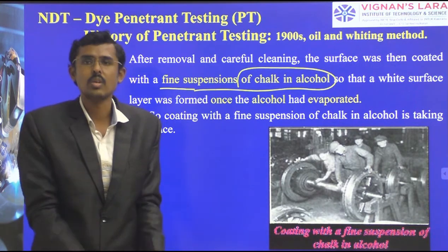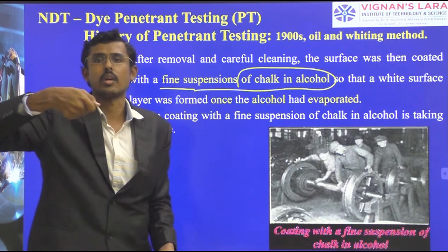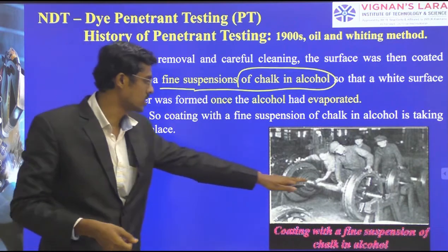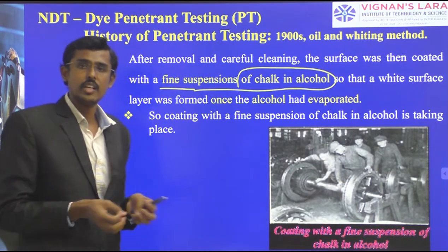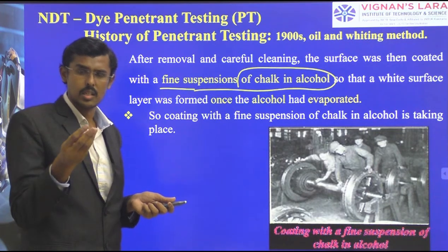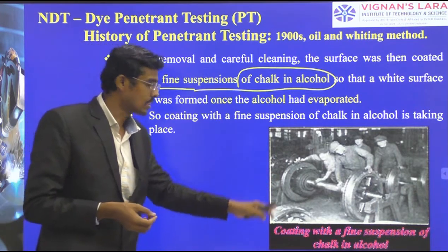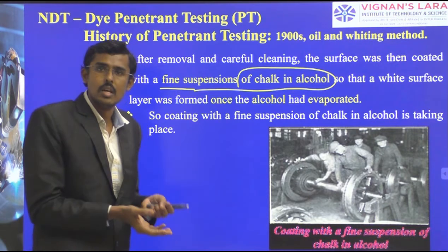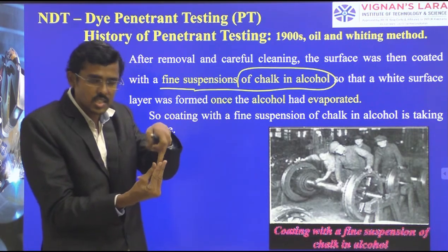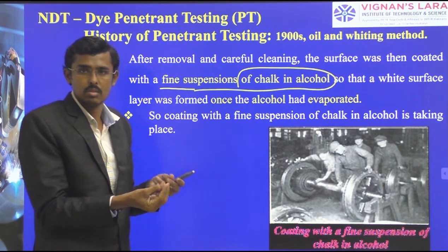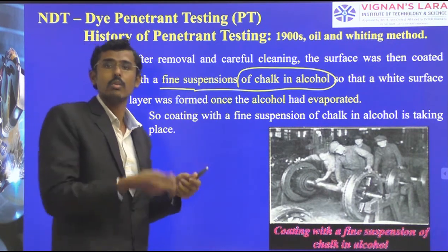The oil on the surface drops down into the tank itself. We have taken out the product and kept it here like this, you see. It is kerosene free because it has evaporated, and the oil on the surface falls down. But the oil which is inside the crack stays inside. So it should come out. How? We have to vibrate it.